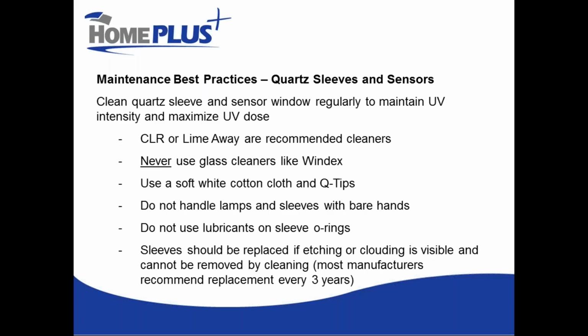A lot of systems like to have extra sleeves on hand, so they pop the sleeve out to clean it. They put their reserve sleeve back in immediately, and then they will soak the sleeve that they've just taken out in the CLR for a little while.